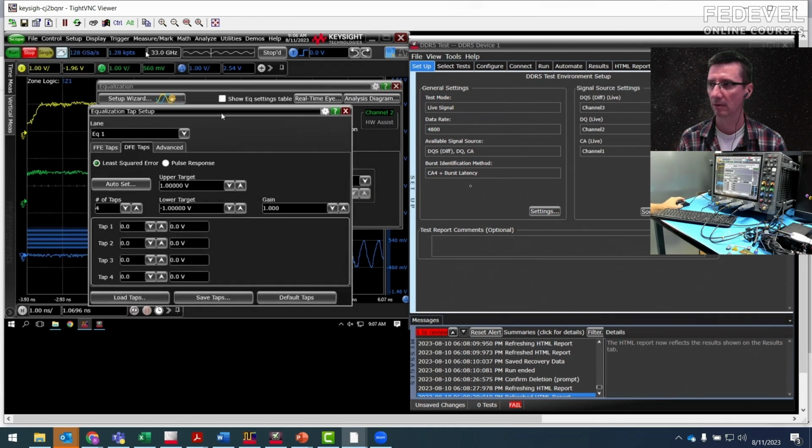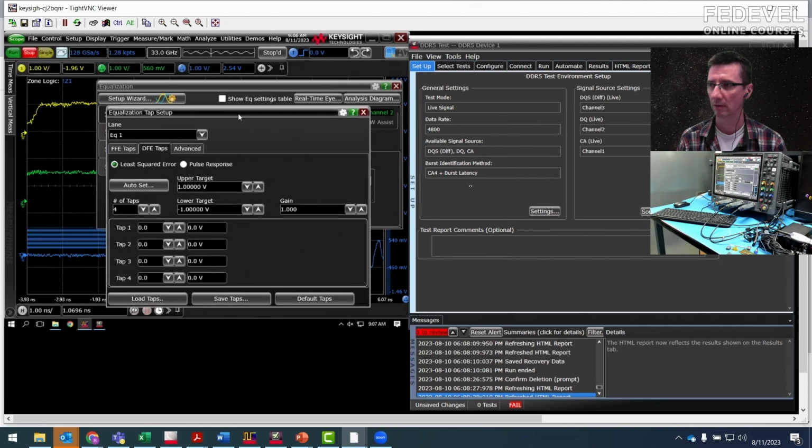Yeah. So in the BIOS, as it initializes it and it does the training, like the write leveling and the read training we talked about, another training is sending a special test pattern that allows the memory to kind of set its receiver, and it says, okay, I adjusted the equalizer a certain way, and it sends a signal back. Is this okay? Nope, not good enough.